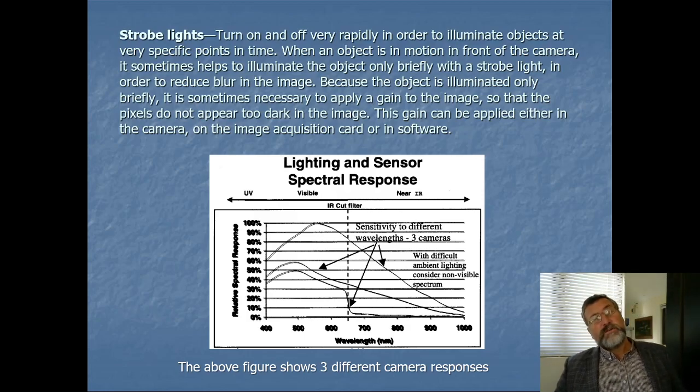This might have been popular years ago, because years ago they used to use TV standards for recovering the images in machine vision. Nowadays, we don't use TV standards for lots of reasons. We get higher resolutions with digital techniques, and we can use any resolution we want and just capture the image when we want to, rather than capture a series of TV kind of images. So we just capture the image when we want it. So nowadays, we'd have the lights on continuously, and we just capture the images when we want to see where the object is. So it's more of a practical approach, really.